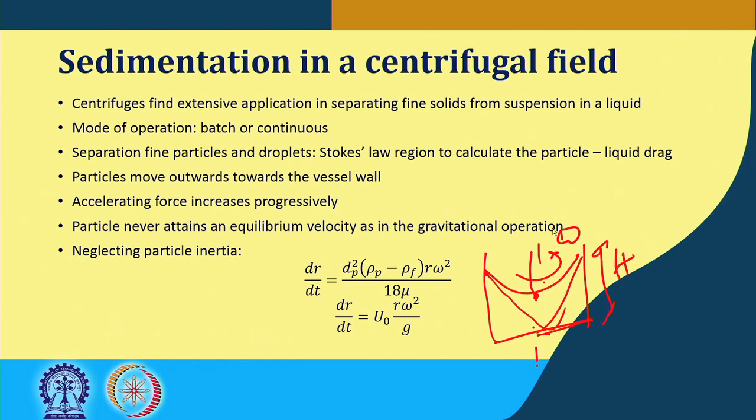So what happens? The particles are then moved towards this vessel wall. The accelerating force increases progressively and the particle never attains an equilibrium velocity, as happens in gravitational operation.